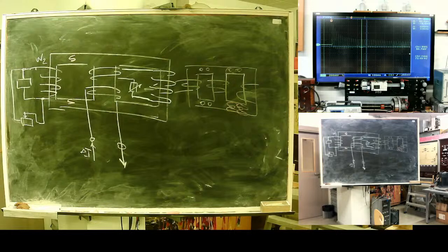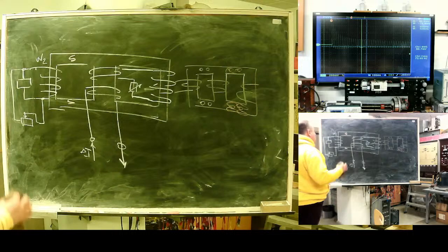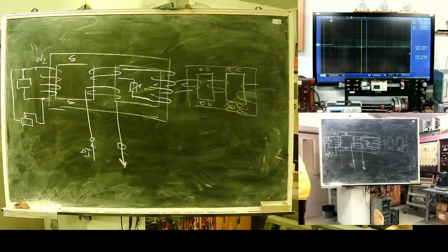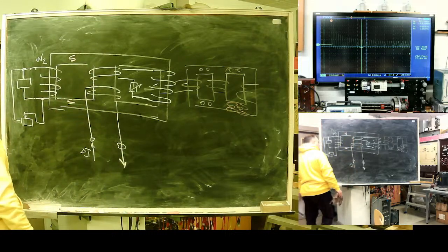How does it work? Strange thing, isn't it? It's a compact design, but to analyze, we can split it. See, this central leg is made wider, and its magnetic resistance is much lesser than side legs plus saturatable areas.